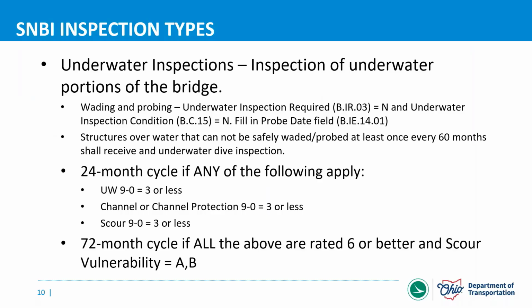So now talking specifically about underwater inspection intervals. Typically, they're going to be at 60 months. That was the NBI underwater inspection interval, and that's how we brought everything over, as 60 months. But we could have 24 or 72 month underwater dive inspection cycles if the following apply. So for 24 months, if any of those underwater or scour or channel related 9 through 0 ratings equal 3 or less, that's going to put you into a 24-month